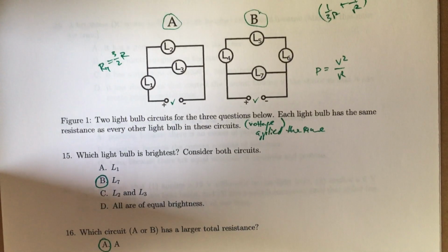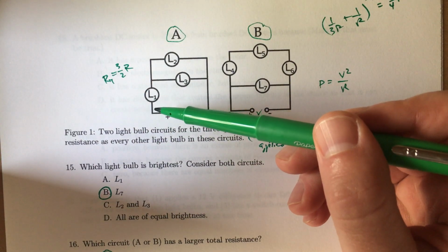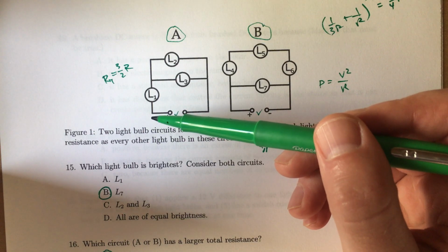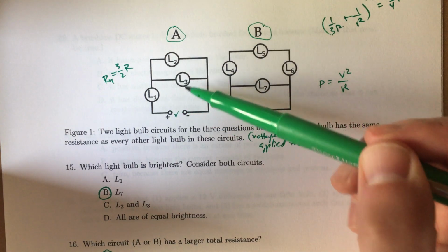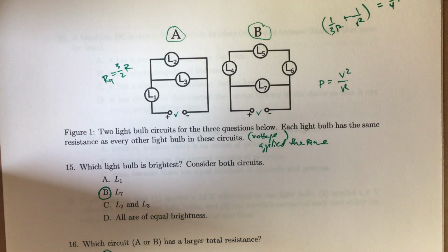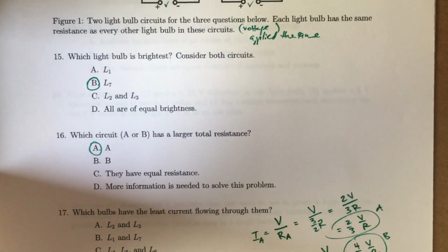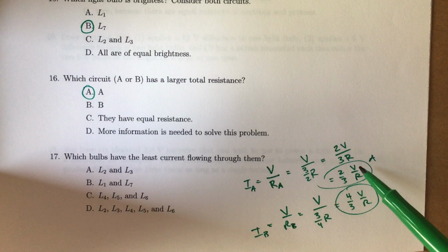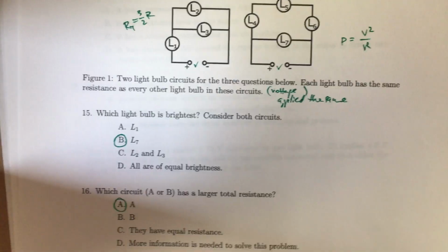If we go back up to the diagrams, well, clearly L1 is not going to have the least current, so we can chop that one off, and that takes care of answer B in the last question on this page. And then 2 and 3 are going to get half of the total current, because they're equal resistance, they're in 2 separate branches, so they each get 1/3 V over R. Okay. And then if we go over here to B,